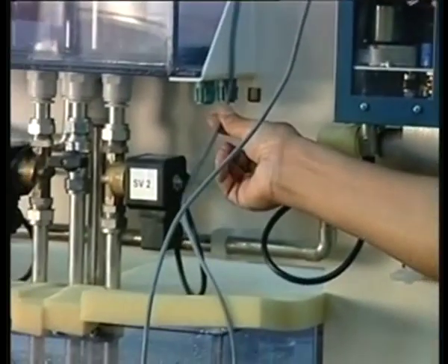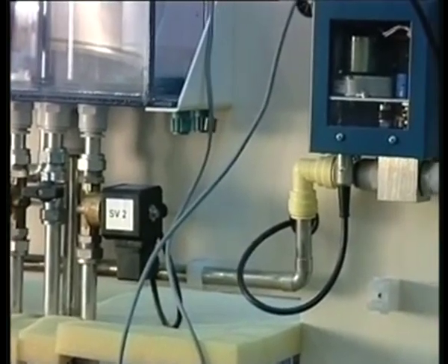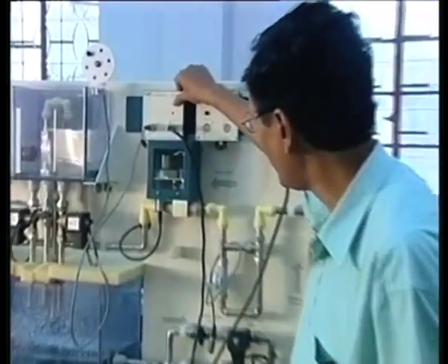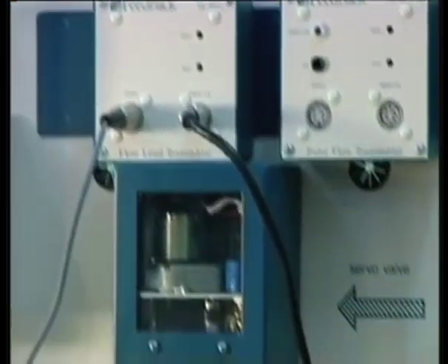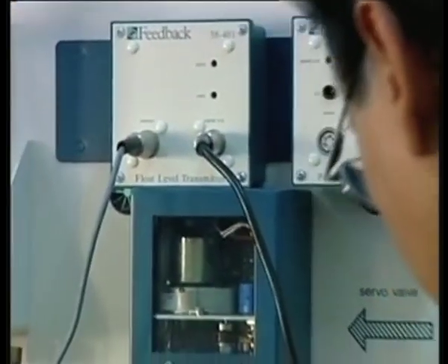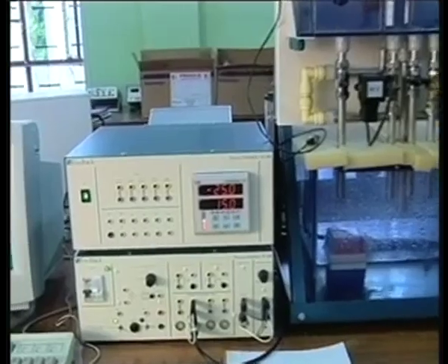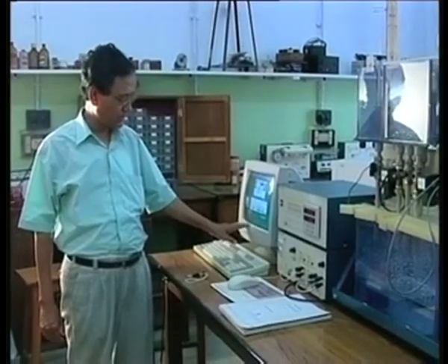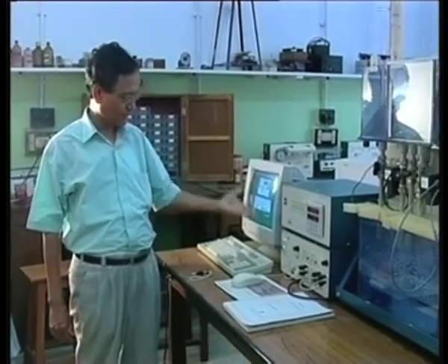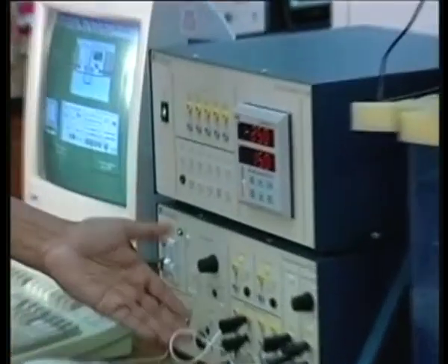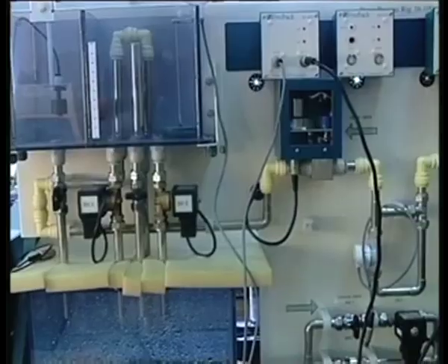In any instrumentation system, one thing you must remember, which will be discussed later also, is that you cannot transmit voltage, you have to transmit current. For that reason, here we have a float level transmitter which transmits a 4 to 20 milliampere current to the process. The signal goes through this cord to the process interface, and from the process interface it comes to the digital computer. From the digital computer there are control algorithms which we can set, and you can tune the controller. It will feed back to the process controller, which will take the action, and then the signal will go back through this cord again to this control valve.